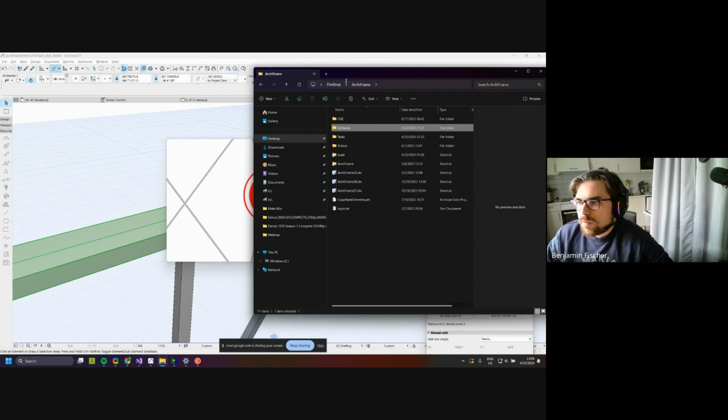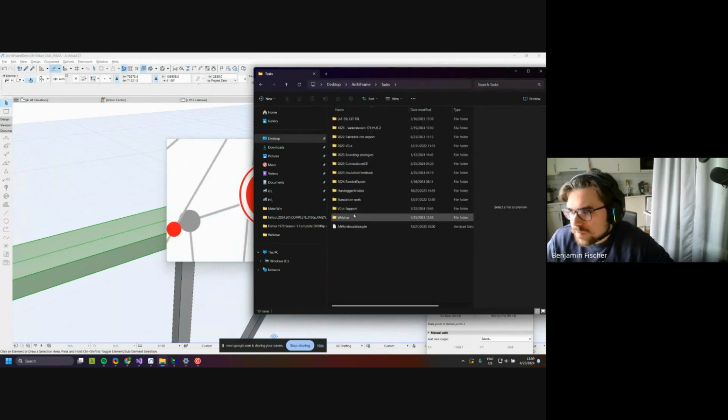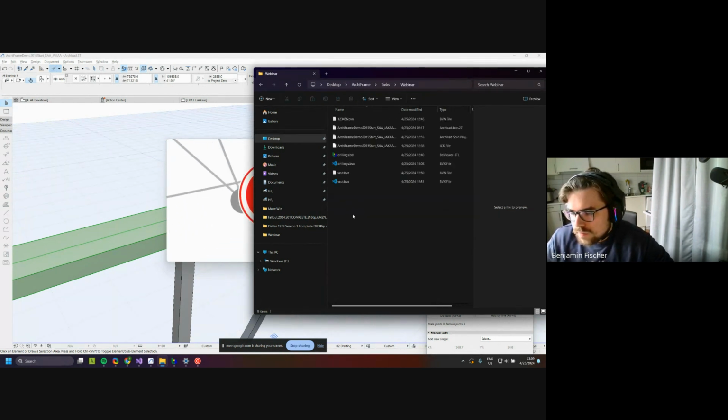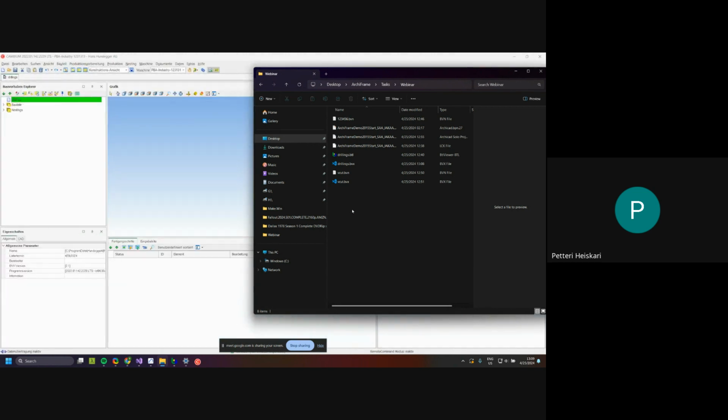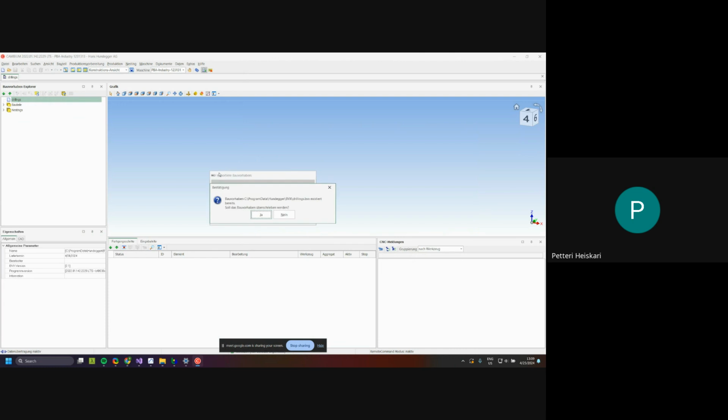Let's open Cambium again. One note while Cambium is opening is that, like the general feature of the groove tool, you can use oversizes. So if you want to drill through, just apply a big oversize to the ends of the plank.